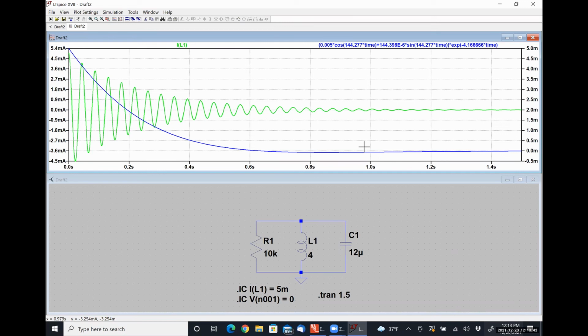That being said, for critically damped circuits, when we have to multiply a coefficient times time at the beginning, for whatever reason, if you put amps per second or something as a coefficient, it doesn't like that. LT Spice kind of freaks out. So I've just gotten in the habit of not including units in checking my result and just making sure that these scales match up.